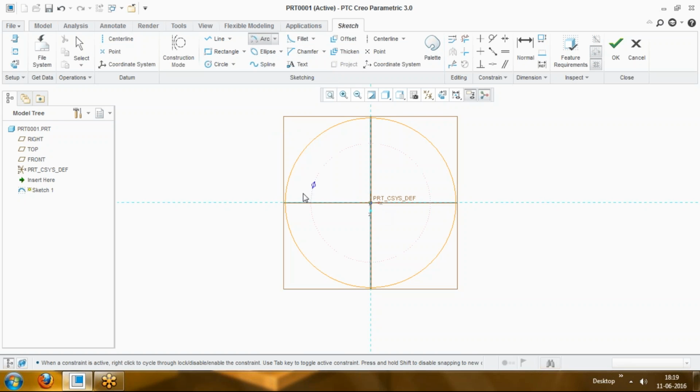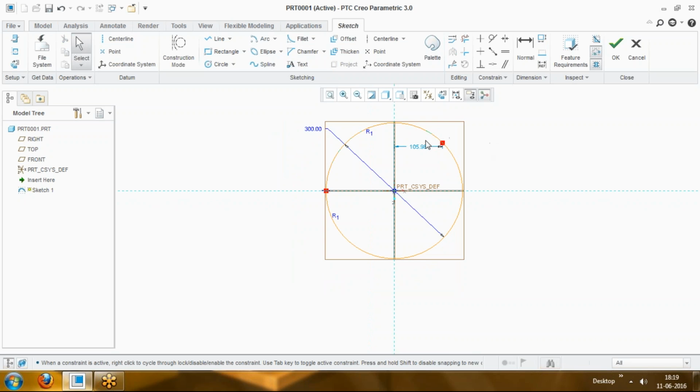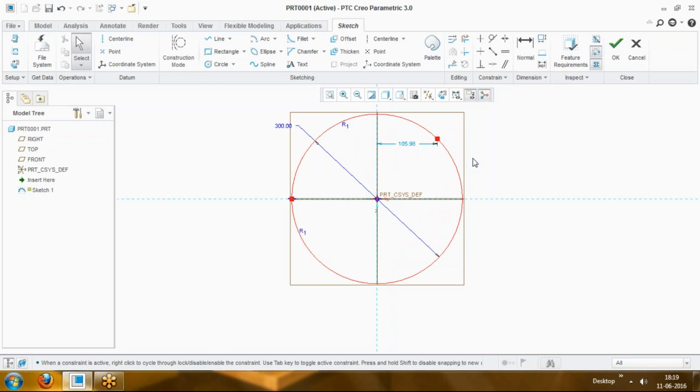I provide the center and the end of this arc. It will show the two highlighted points, which is called highlight open ends. I turn this on, and after that there is the operation called select overlap geometry. Pick this, and we will see if there is any geometry overlapping each other, so we can turn it off.